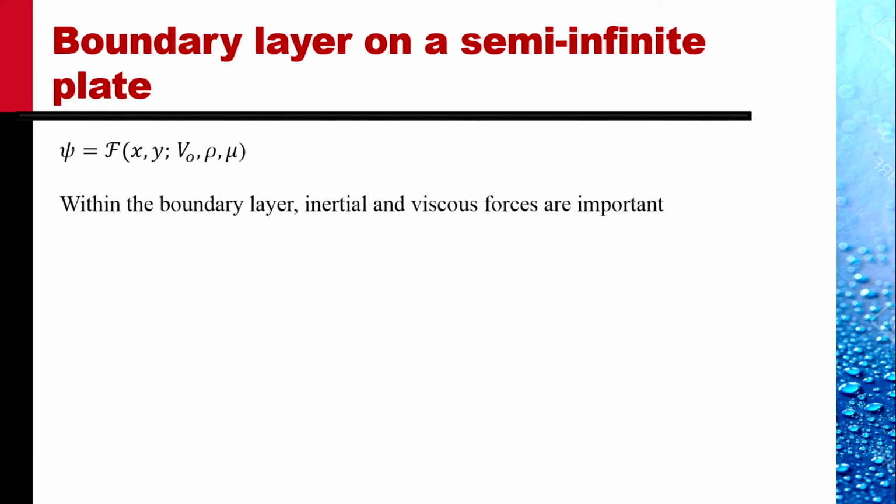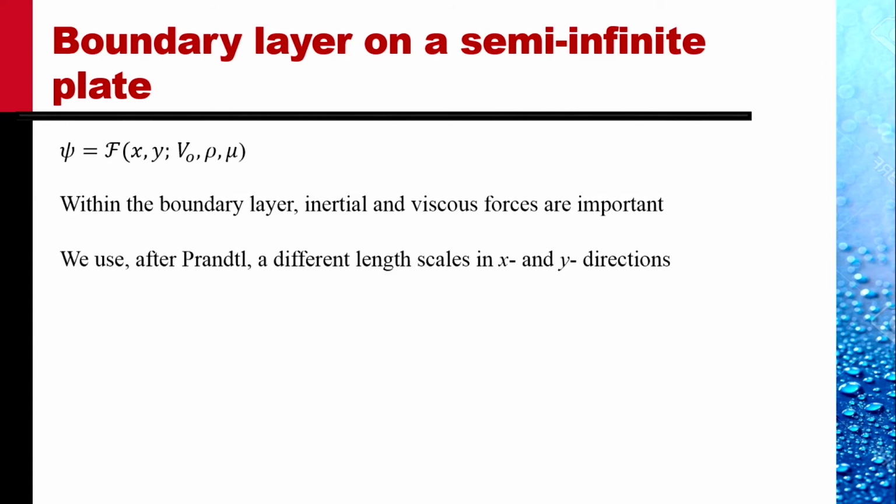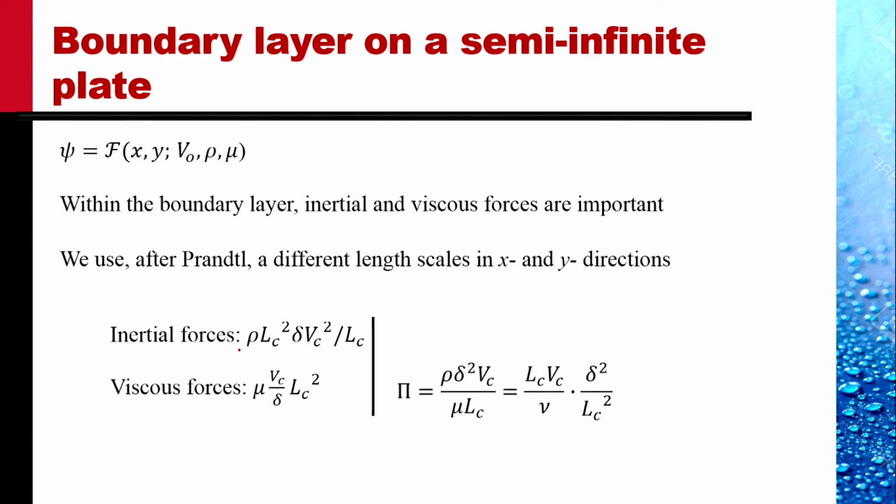Within the boundary layer, viscous forces cannot be neglected, as postulated by Prandtl. This means the inertial and viscous forces are important. So we consider these two forces. Inertial forces are like mass and the convective acceleration. Now we have used, after Prandtl, a different length scale in the x and a different length scale in the y direction.